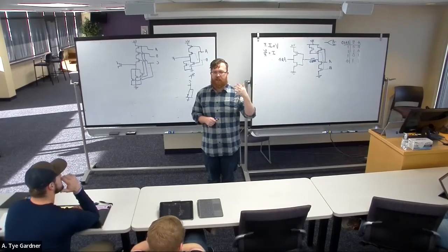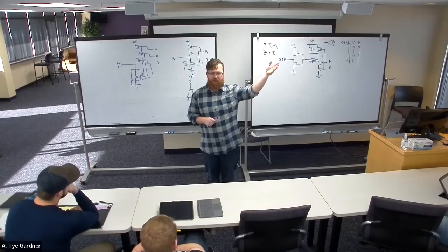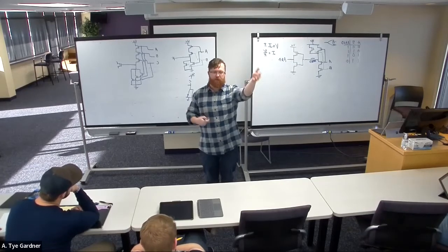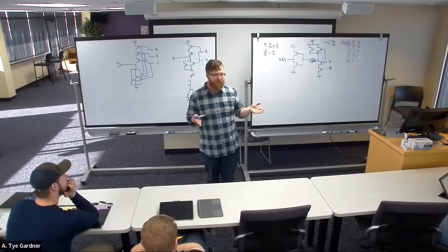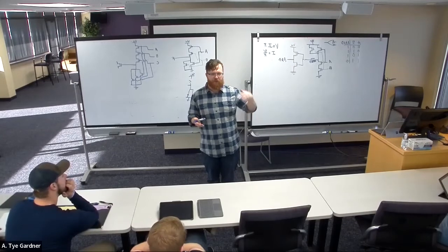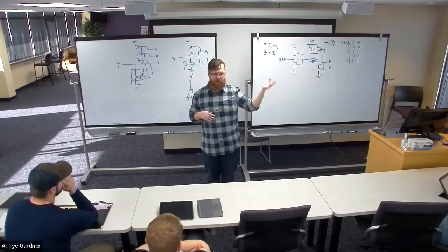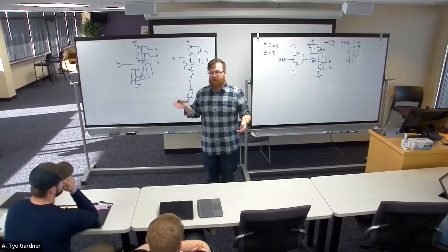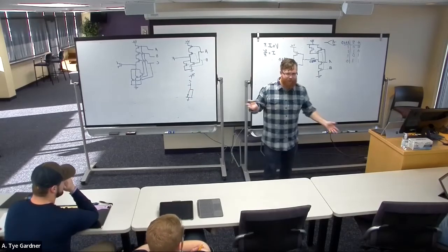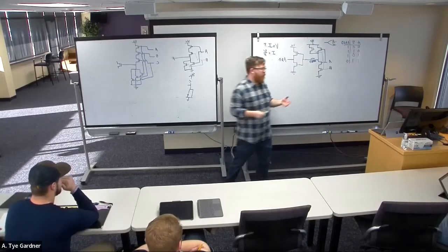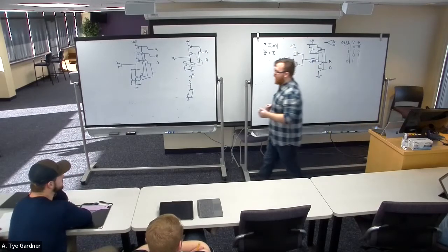So what happens is, let's say one device, it's its turn to talk, so it's going to send a 0 or a 1, and the other device is going to listen, and then it's going to go, okay, it's my turn to respond, and it's going to start sending data. The problem is if they try and talk at the same time, they might break. If one sends a 1 and one sends a 0 and they're talking over each other, it gets noisy and we don't understand. That's also true, but in the case of digital logic, they light on fire as well as don't understand, which is problematic. So we have an ability to prevent this from happening, and it's called open drain.